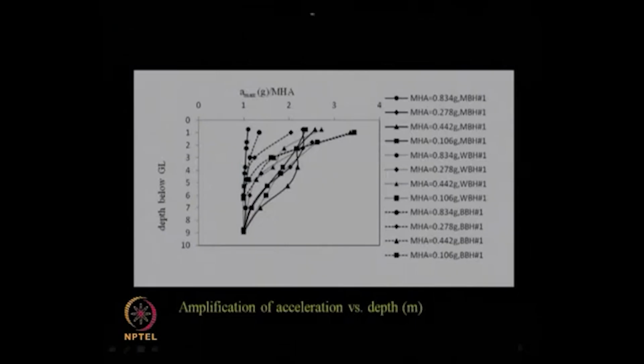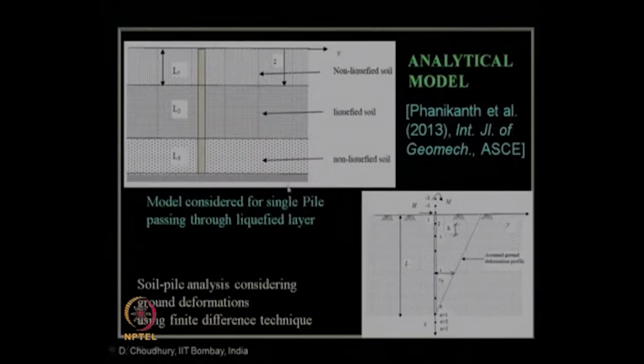The purpose was to find out how much amplification occurs from the bedrock level to the ground surface through various layers of the soil, how much amplification of the seismic response or acceleration is going to occur due to the soil properties, through the ground response analysis using deep soil. Now, when we were discussing the pile analysis, Dr. Phanikanth had chosen a single pile analysis, the behavior of a single pile, which is passing through, suppose, these 3 layers.